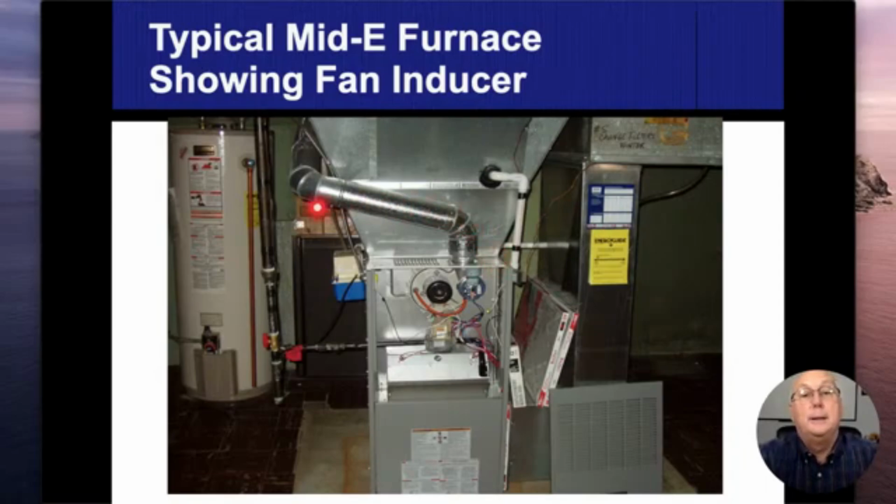But I am going to be looking for signs of condensation on all of these joints. Any sort of dripping or anything that's going to show where I have any sort of bad drafting, and I'm going to be aggressive with it. Right, this is a gas furnace. We do have gas pipes here on the left coming in. And so we know we have to have a 6-inch clearance to our single wall pipe that goes up in here. And this orange hose that we're looking at, that's what connects my inducer fan to that pressure differential switch. And as long as that fan's spinning, I'll be able to create a positive pressure, and this switch will sense it.